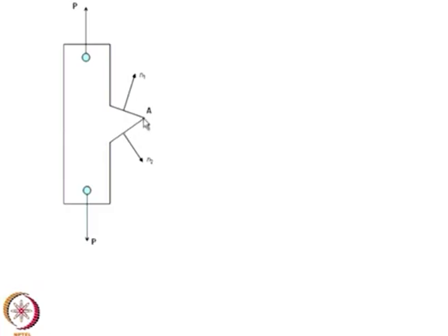I would like to know what the stress magnitudes are at the sharp corner A. Can anybody say? Suppose instead of this corner I have a cutout here, then it acts like a V notch, and you have singularity at the crack tip, at the angle and so on; you call that a re-entrant corner.